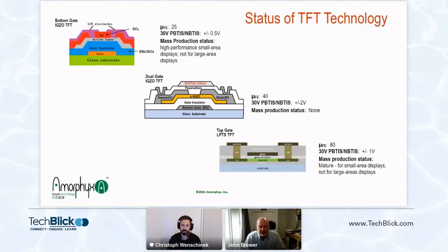After 15 years of development, IGZO is in mass production in a subset of premium-grade smartphones, tablets, and monitors. But its improvements in speed, output current, and power consumption, incremental on silicon, are of limited value as manufacturability and physical size compromise its broader applications. Next slide, please.